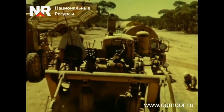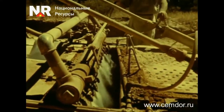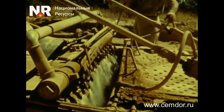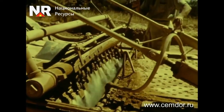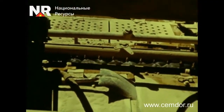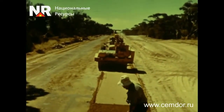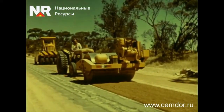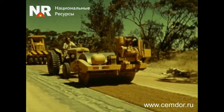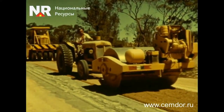The required amount of water is supplied from a tank moving ahead of the mixing unit. If necessary, a stabilizing additive is introduced which can affect the water balance of the soil cement system. To achieve maximum density and therefore maximum strength, the soil cement must be compacted as soon as possible. After mixing, the roller should follow immediately behind the mixing machine. Vibratory rollers have proven extremely effective for the initial compaction of certain soil types.